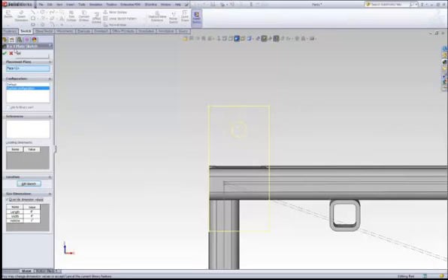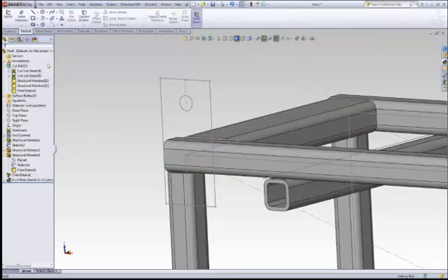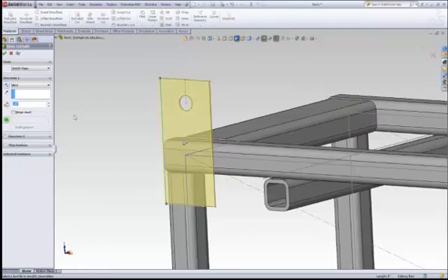If you want to know more about using the design library, it's probably not a bad idea. We probably won't have time to cover this during this presentation. And then once we have that sketch in there, we can go ahead and extrude it. Notice that, again, by default, the merge result checkbox is turned off, so it becomes its own body.